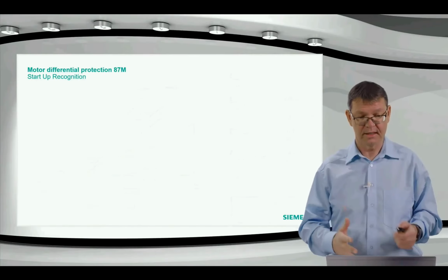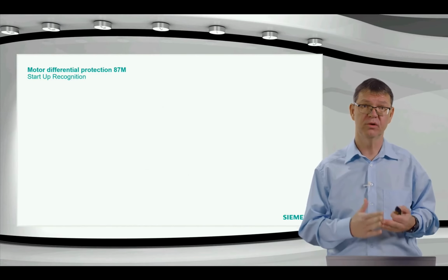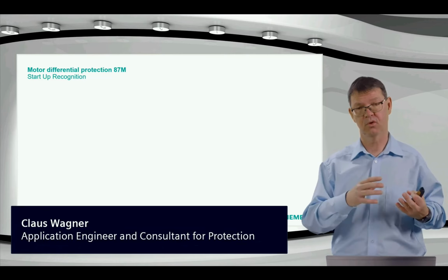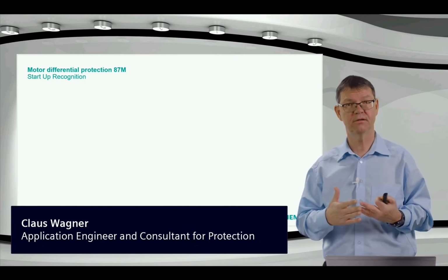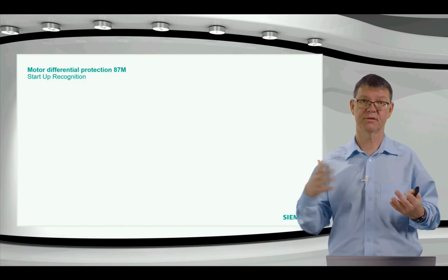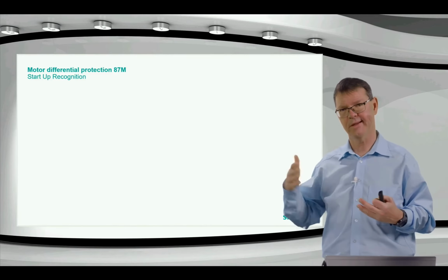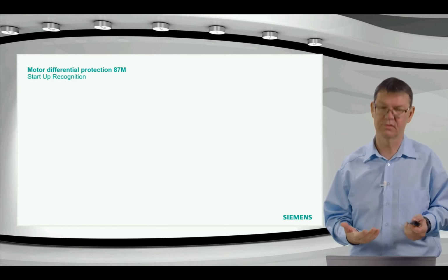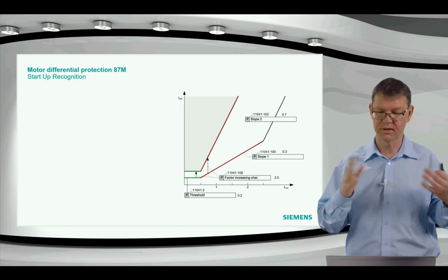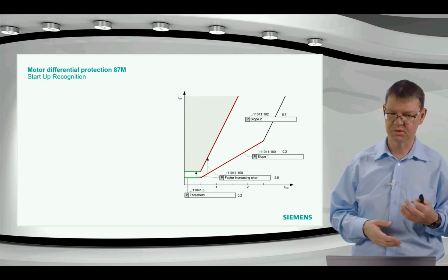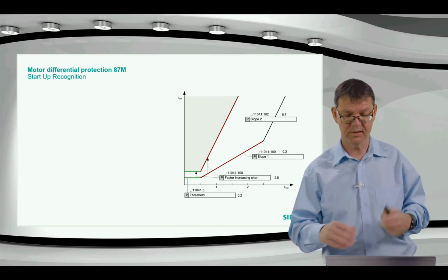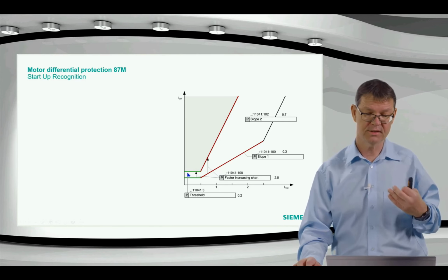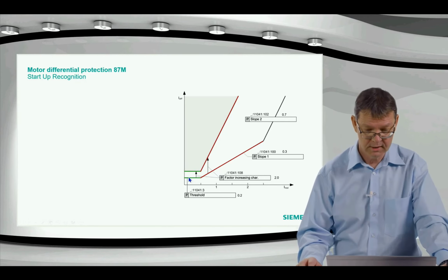Good. Startup recognition is a special function only for the motors, because there we have to deal with a long time of elevated currents during the startup. So I said this can take seconds, 10 seconds, 20 seconds, and this could stress also current transformers. And we found here and there problems with the current transformers. So therefore we have the possibility of this startup recognition and to react when we see there's a startup of the motor.